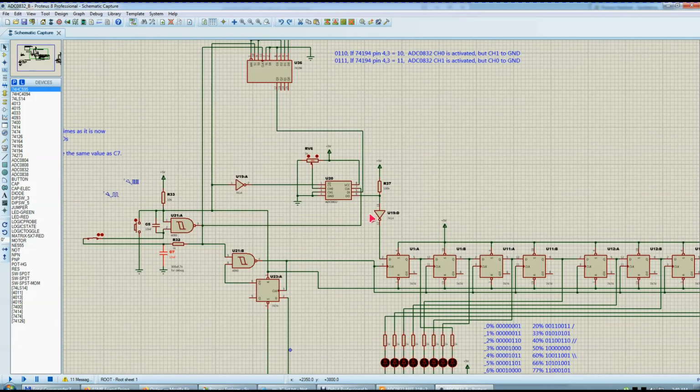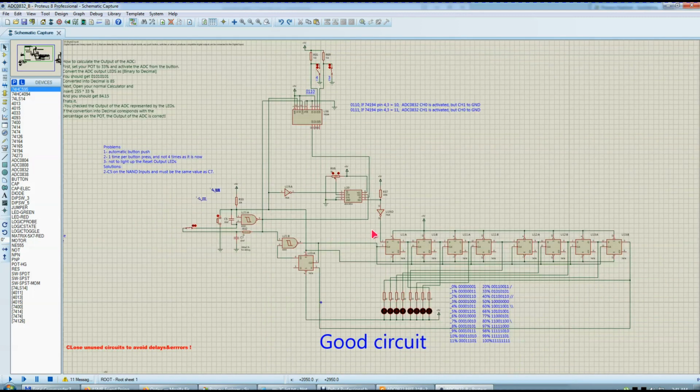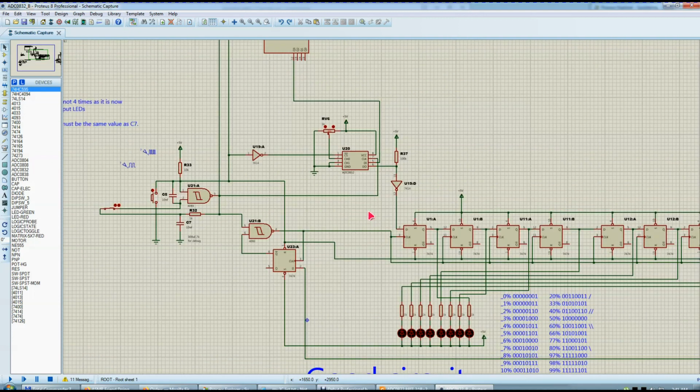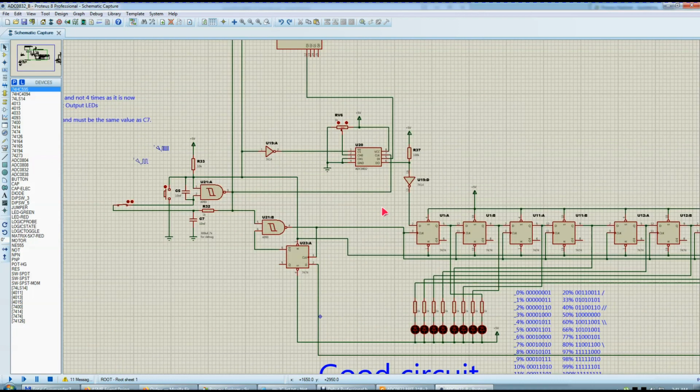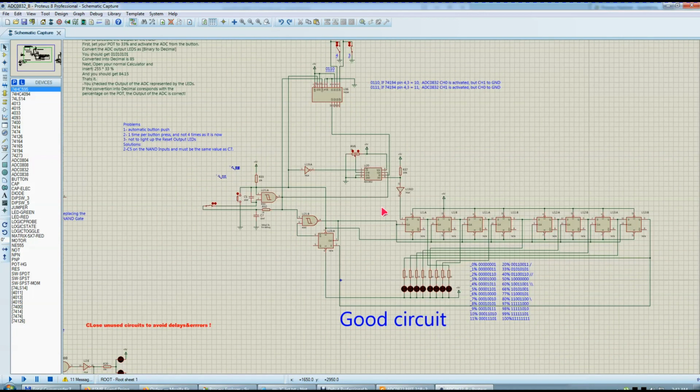So this is his explanation why I get this erroneous effect when I'm clicking. Sometimes when I'm clicking, I'm getting the error, and sometimes when I'm clicking, everything is working fine. That's very weird, at least here in Proteus, where everything should work at a lower frequency. If I increase the frequency too much, Proteus will give me errors. It's not made for very fast frequency, but it works absolutely fine with lower frequency. It's a rule that I learned in time by using this software. So it's my experience that I'm talking from.